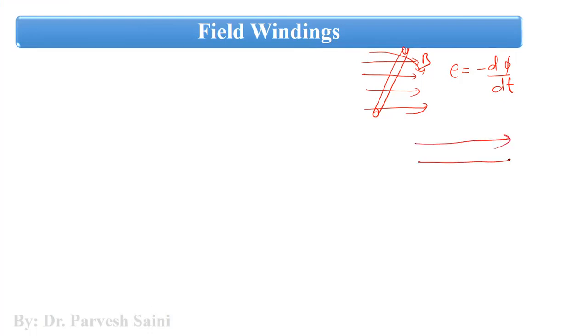You have magnetic field, you have conductor, right? But this conductor is already carrying some current. So we have current carrying conductor placed in magnetic field. So this conductor will experience a force, and we will get some rotation because of the torque generated in this particular conductor. So this is the motor action. Okay. So now that means to have the generator action or the motor action, we need a conductor, we need magnetic field, right?